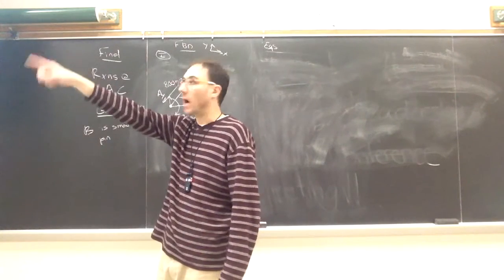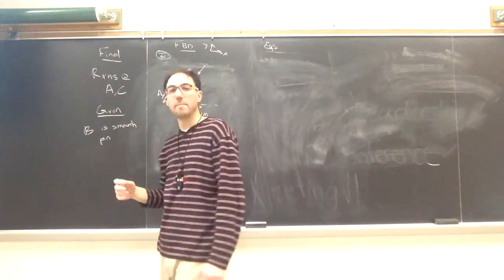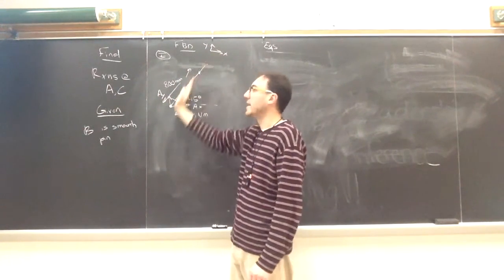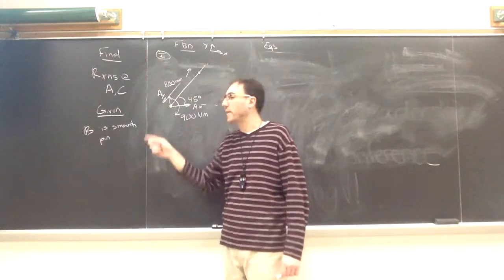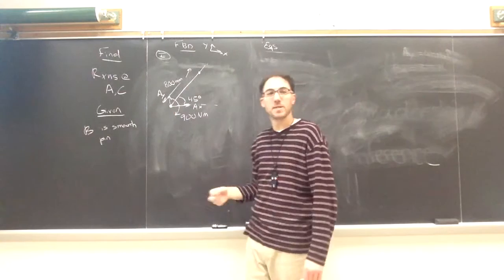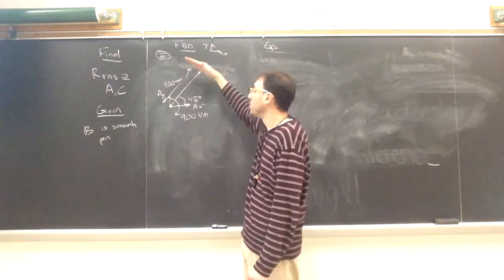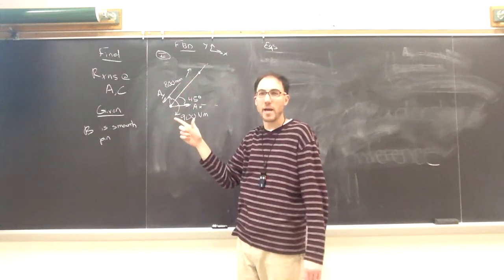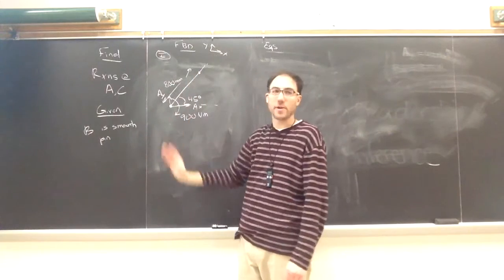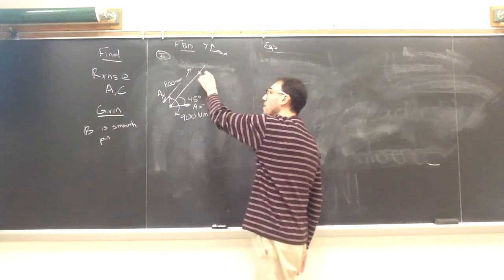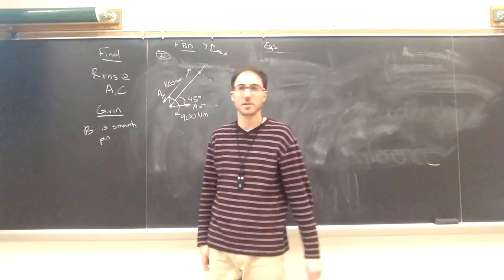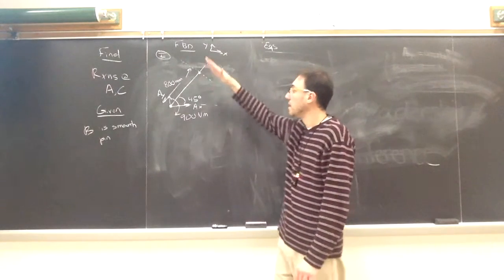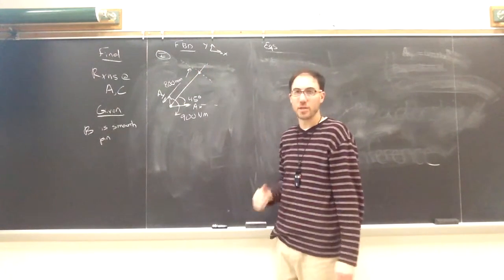It can move along the direction of that slot. So it can move along a 45-degree angle. The peg does not prevent that motion. It can slide inside that slot. So at 45 degrees, it can move along this line. So specifically what that peg prevents is motion normal to the direction of that slot. So it's not as easy as just saying X or Y, because it can move at 45 degrees, but what it cannot do is move perpendicular to the direction of the slot. So in this case, it's a single force. It only prevents motion along the axis perpendicular to the slot.